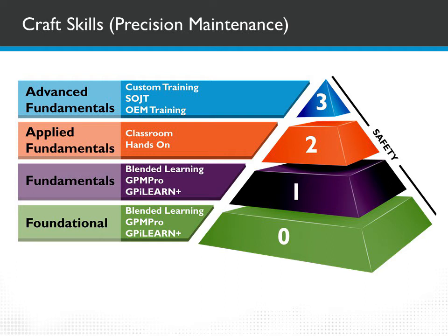And then a big part of the process tying into reliability that people often forget is the operations side. The operators are the first line of defense and also know the equipment the best. So frontline reliability is a priority in the process of reliability. Having your operators be proactive in doing inspections, providing basic troubleshooting, even changing filters, is really a proactive approach to finding issues and eliminating defects. So having a frontline reliability process, we feel, is critical in freeing up maintenance to be a more proactive force.